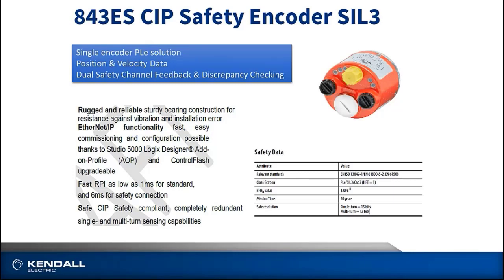The add-on profile and ControlFLASH upgradability allow us to do quick, easy upgrades and integration with the PLC like we'd expect from Rockwell devices. We can get up to 1 millisecond communications, RPI, to our standard PLC, so we can get speed and position monitoring from the encoder back to our standard PLC control to program in for conveyor movement or anything like that, while also getting a 6 millisecond RPI back to our safety PLC.